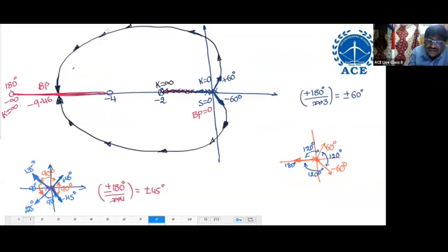Then one pole, this is the pole's path. Root locus branch means pole's path. So once they enter, how many poles enter? 2 poles. One pole moves towards one zero, another pole moves towards another zero. This pole moves left and occupies the zero when k equals infinity.